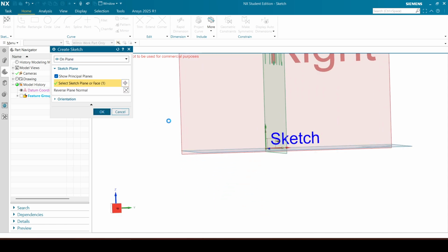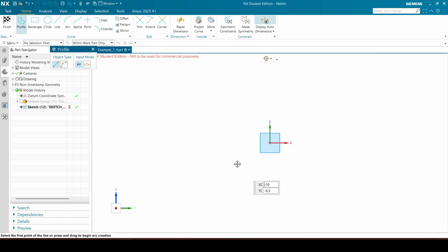On the right view, I'm going to start with the profile and leave out the center hole. I'm also going to leave out what I'd call spoke cutouts, or rim cutouts. So I'm just going to make the basic outer shape, and the chamfer I'm going to add later as a feature and not build it into the sketch itself.